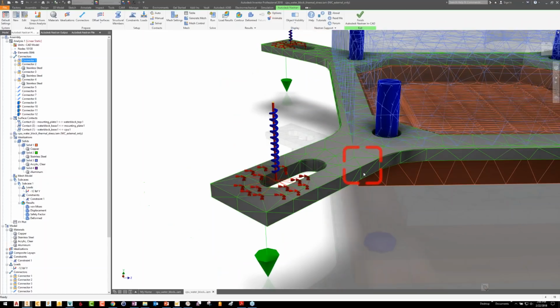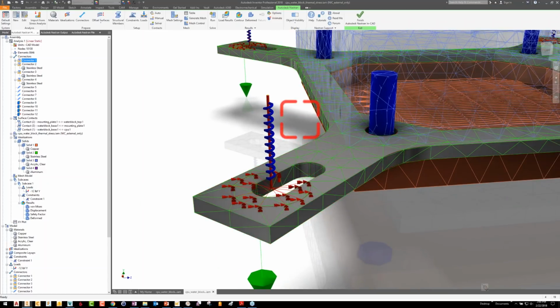This spring normally is coiled around the thumb screw, which kind of keeps it positioned in an axial Y direction, right? And there's nothing here anymore to actually do that. So this spring could technically go off in any direction and cause me all kinds of singularity problems. So I need to constrain it. But I don't want to constrain it so much that it's no longer allowed to move.